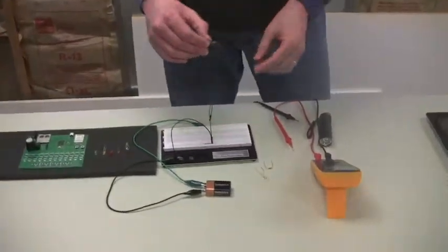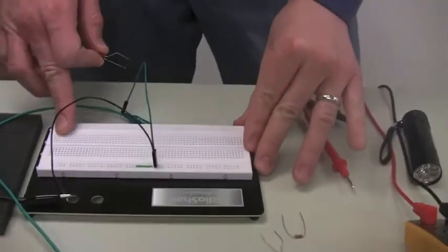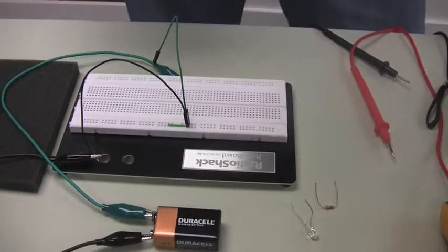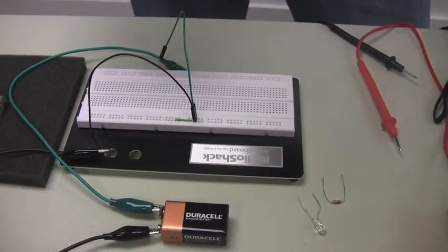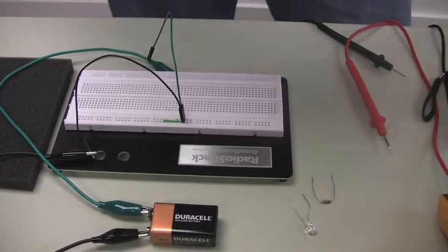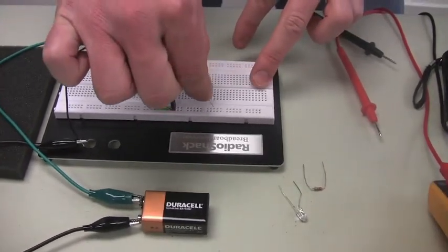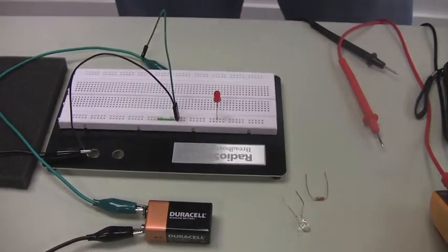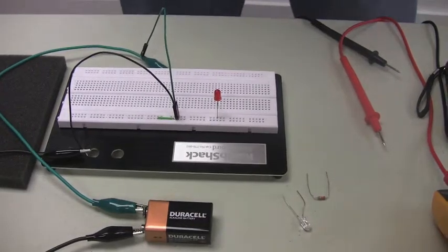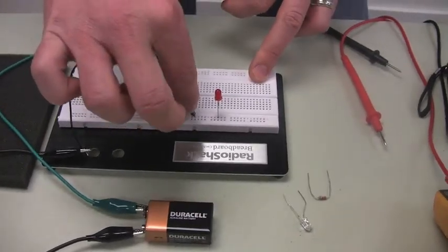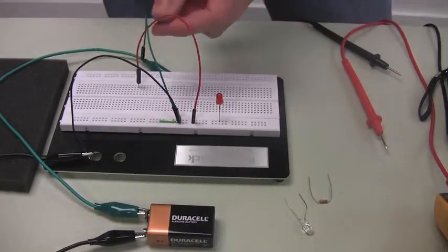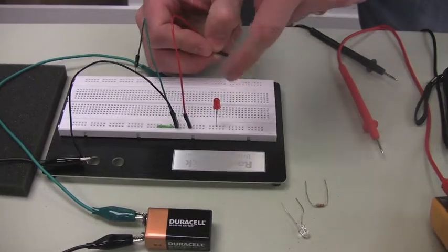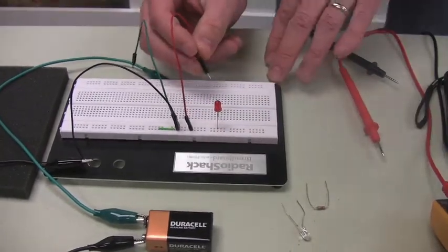So the first thing I want to do is come down here to our breadboard. I've got the same setup that we've been using in some of the other episodes. I got a 9-volt here. What I'm going to do is connect the negative side to ground, and I'm just going to leave the positive side out there. And then I'm going to take the positive, put it in here, and complete the circuit. So current's going to flow out of the positive through the LED back to negative. It completes the circuit. Let's see what happens here.